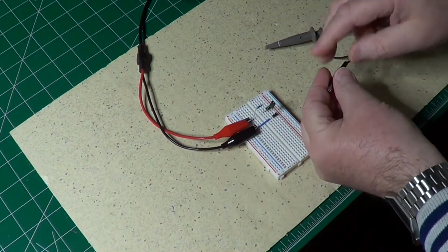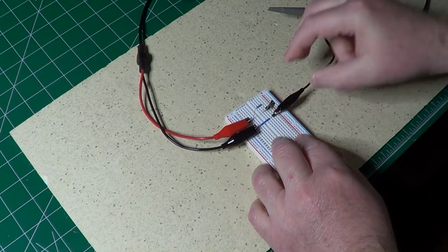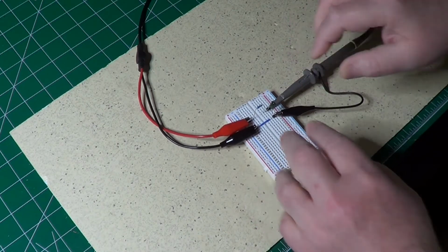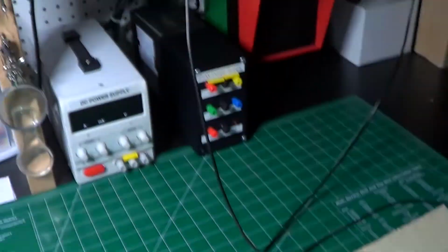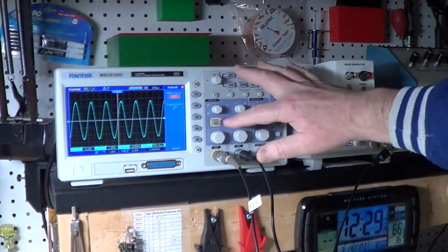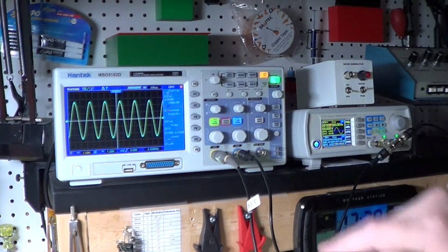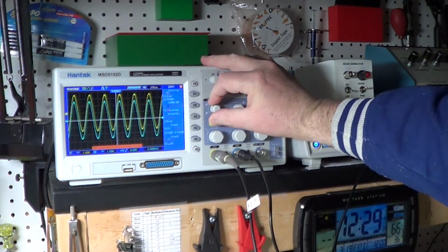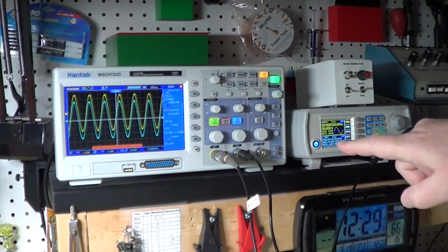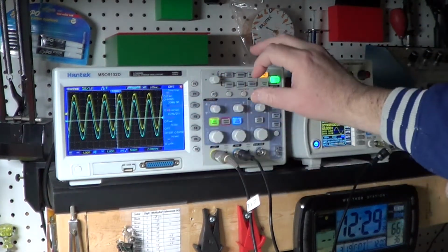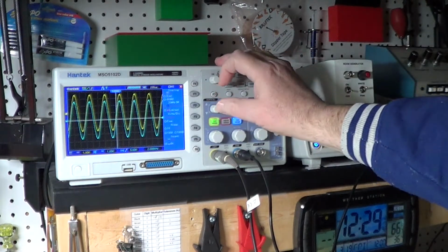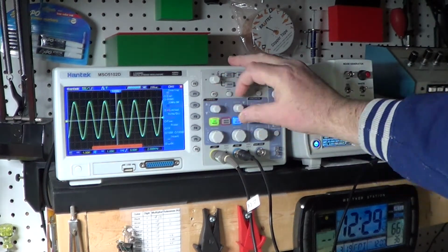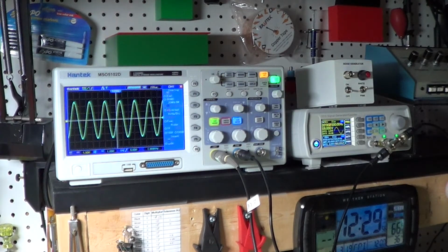And so we only put the ground here again, and the output is connected over here. Now let's go back to the oscilloscope and activate the other channel so we can see both of them at the same time. You see right now they're almost superimposed. Let me shift them a little bit so you can see the difference. So the yellow now is the output of the filter, the blue is the input of the filter. Let me leave them superimposed so it will be easier to see what happens when we change the frequency.